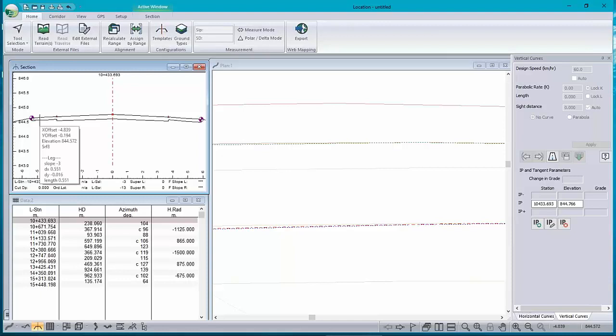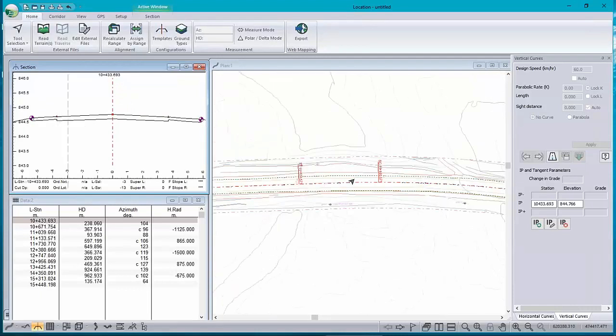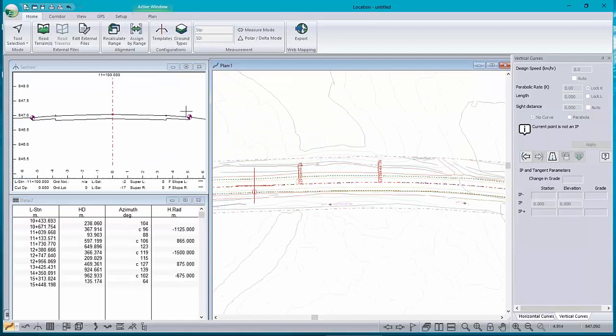So it's automatically calculating where the milling needs to go to. If I look at any place on my alignment, it's lining up with those surveyed lines. The depth is determined by the template. Hopefully I've got them right, and it's not going to go too deep and cut through the old pavement. That's always a mystery. Depends how well it was laid down.